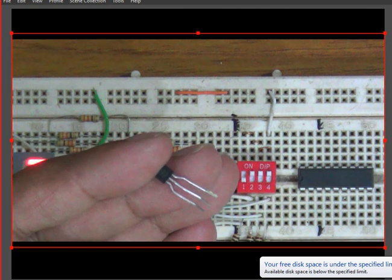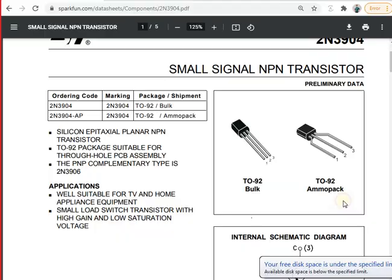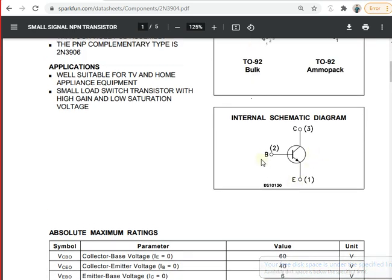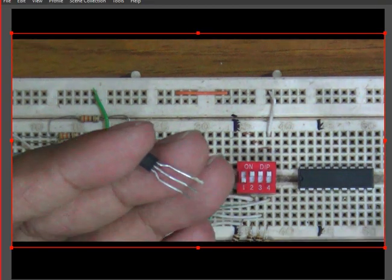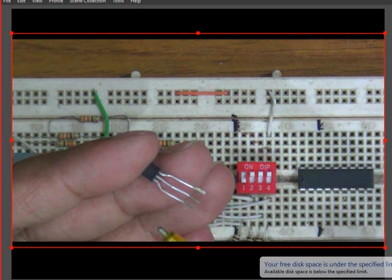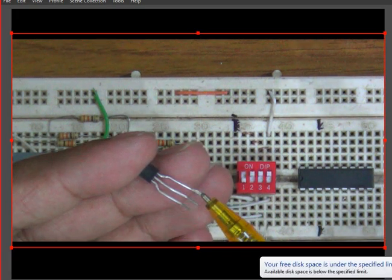So if I go back to my data sheet, what is pin number 1? This is emitter. What is pin number 2? That is base. What is pin number 3? Collector. So EBC. Normally, whenever you want to remember any data sheet like this, it's better not to remember the whole name. Just see the initials. So E, B, and C. If I go back over here, this was pin number 1, pin number 2, and then pin number 3. So this is E, B, and C.